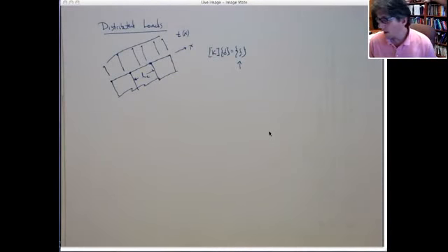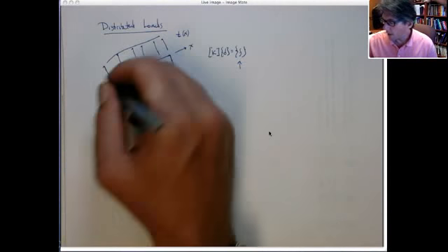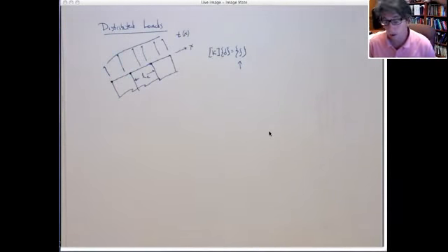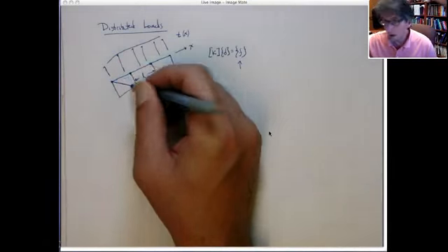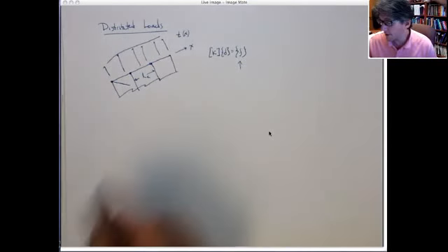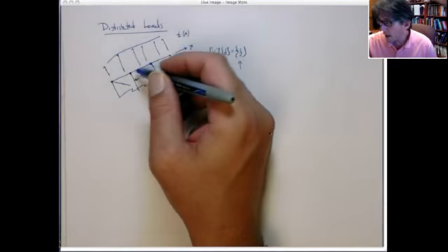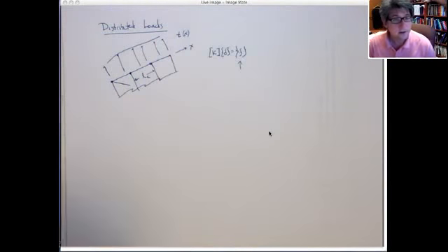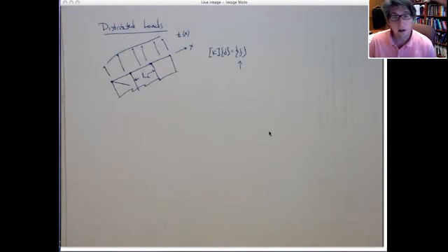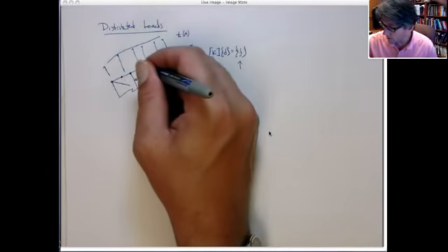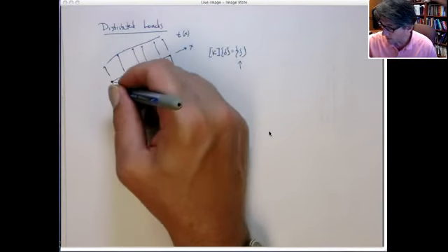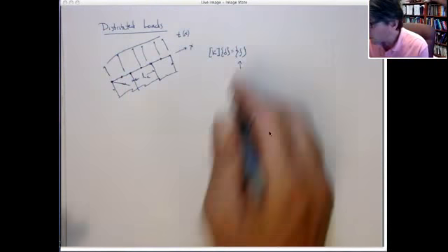All right. Now, as it turns out, for elements that have two nodes on an edge, like the Q4 or even the constant strain triangle, what you find is actually you put half the force on the edge onto one node and half onto the other node. There are actually a couple of subtle differences with that, and also when we talk about elements that have more than two nodes, we don't just divide it up into three, okay? So I want to talk a little more rigorously about how we handle these things. All right. So where does this come from?